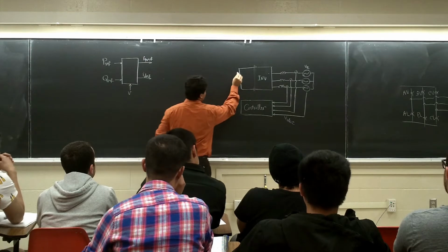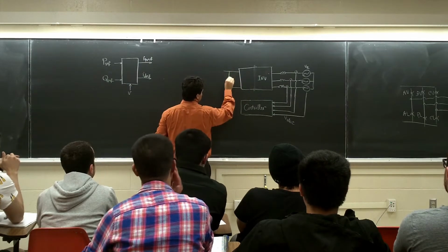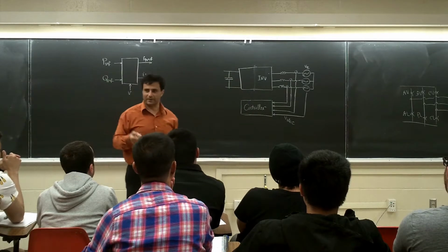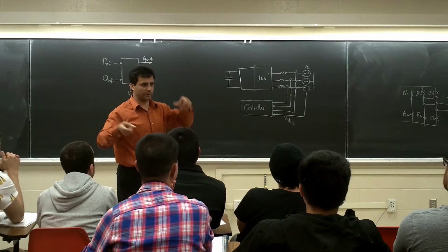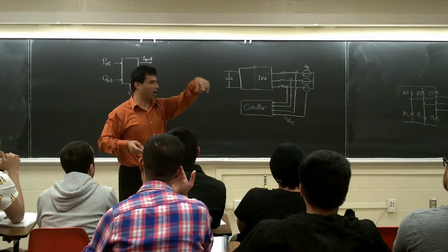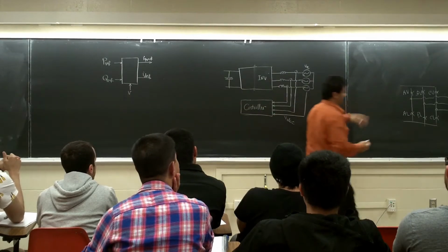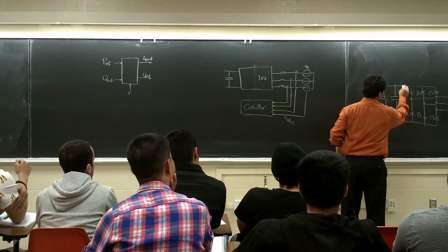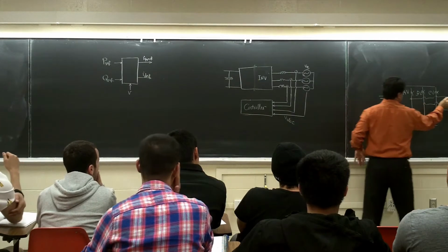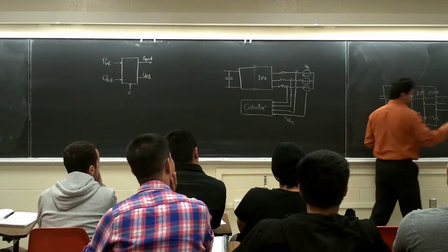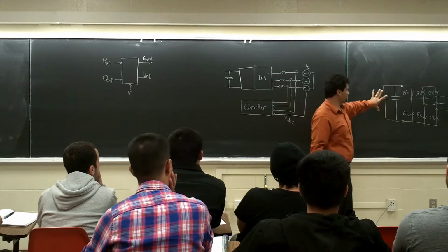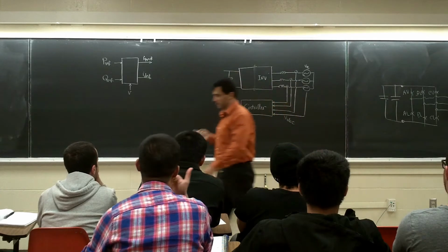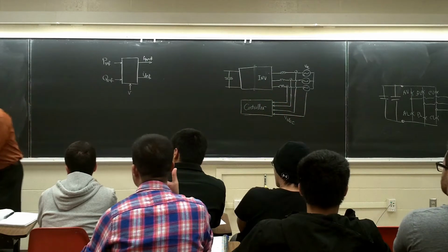Now, this is a DC cap. On that inverter, I didn't put the DC caps, but if you look at the DC bus here, externally I can put my capacitors here. Right? These 2 points are available on that board. So I can connect my capacitors here. So this is where I'm connecting my capacitor. You can pass this to me.